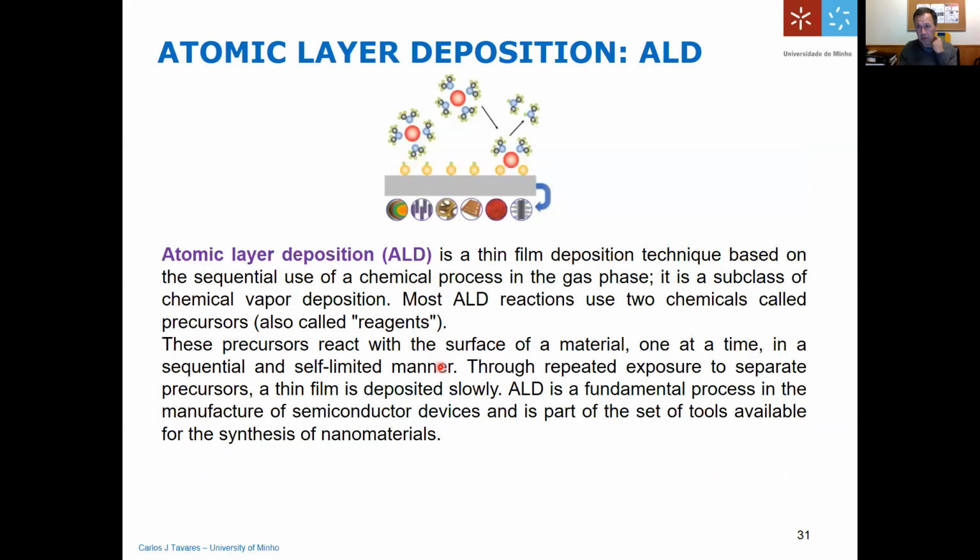Now I'll conclude my talk by speaking about atomic layer deposition, which is another process of chemical vapor deposition, but it's more sequential. It involves the inlet of a precursor gas and the purging of the gas, and another type of gas to remove specific elements or molecules that you already have on your substrate. And so this is called atomic layer deposition.